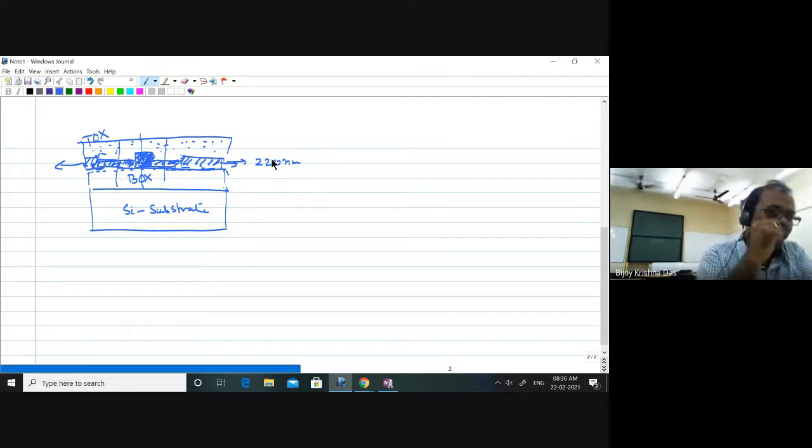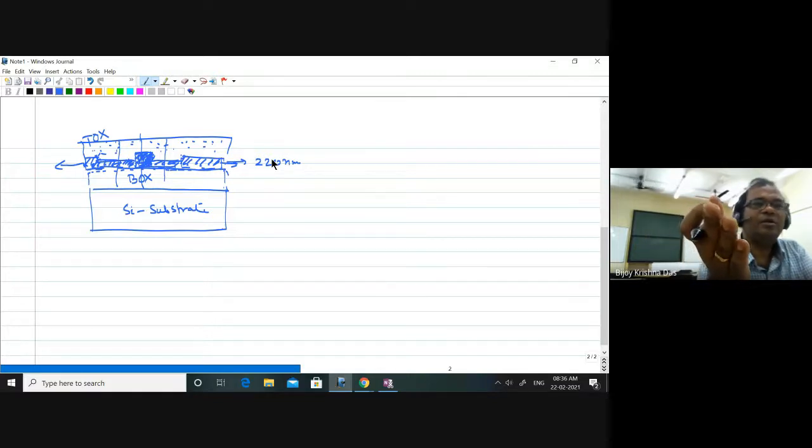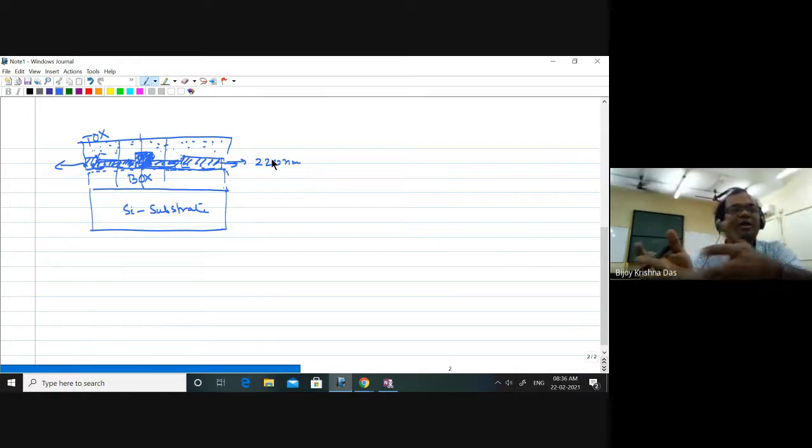But for designing an optical waveguide, you have to keep in mind that your waveguide cross section, or feature size dimension, can be smaller, but ultimately you rely on the optical waveguide for your device design and circuit design, and for that you need longer lengths. As you maintain the cross section over a longer length, your light will be confined and you can bring your light anywhere.